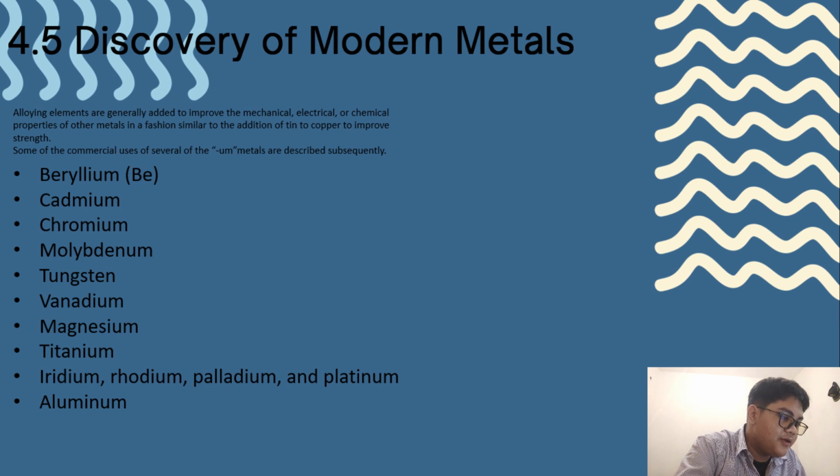And then cadmium. Cadmium was discovered in 1870 and is primarily found in zinc ores. Cadmium coatings or plating were used to protect nuts, bolts, and other components made of high-strength steel or other relatively corrosion-prone metals. The cadmium plating acts much like some paints and limits the access of environment to the protected component. Many of the components in commercial aircraft are cadmium plated.